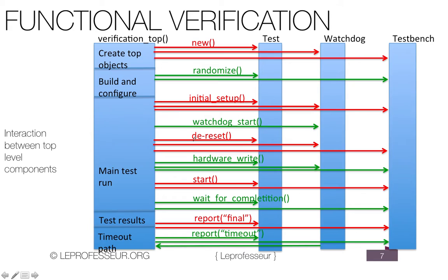And then you start or deassert the reset for your chip and start writing to your hardware, and your test is running, whatever test you are doing, and then some way to store or report out the results in a report format, and then timeout paths, okay, so that you can go further and analyze, right. Here somewhere you will also write a coverage component, but that coverage component is a facility the language provides. You can embed those things in your class when you write the class, so it's easy that way, okay. So don't be afraid, it's very easy.